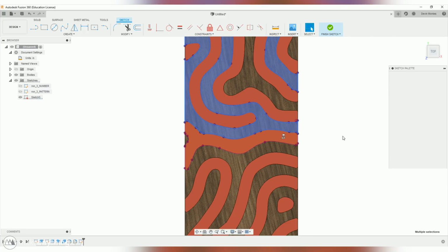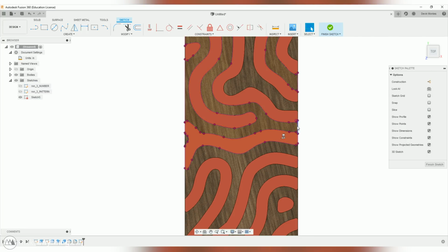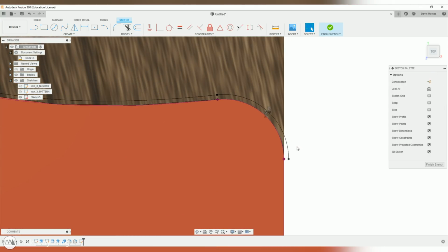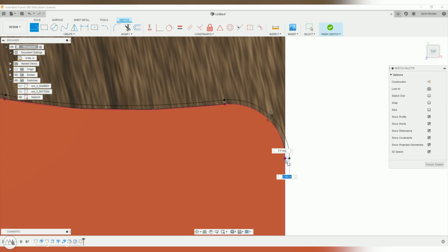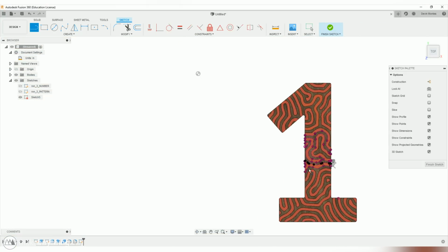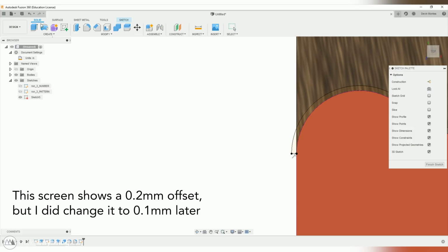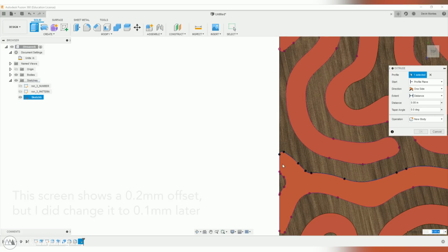I thought the best way to do that would be to hide the split along one of these organic curves rather than just having a straight cut through the model. So I'll use this red line that's going right across about halfway through the one, and I'm gonna create a 0.1 millimeter offset and cut away that little sliver to split this model into two parts.